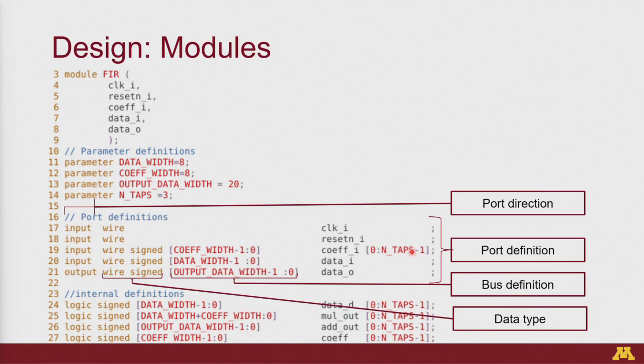An unpacked dimension just means that you have multiple of these wires. Each one is independent of the other, but within itself, the packed dimensions are all connected to each other. The unpacked dimension is what you truly think of as an array in your other programming languages, like element 1, element 2, element 3.